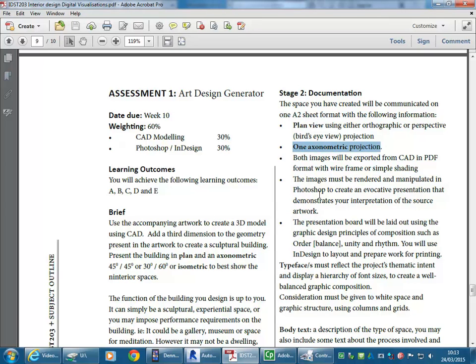So do you all know what an axonometric view is? Angled, yeah. Measurable. It is measurable, yep. Why is it measurable? Yeah, sorry? Yeah, it can be 45 degrees, it doesn't have to be. So the 45 is when the angles are equal, and that gives you basically an isometric. But an axonometric just needs to have a vertical axis. So the axis is at 90 degrees, and then the other angles can vary, but they often are. I'm going to do it at 45, also equal angles.